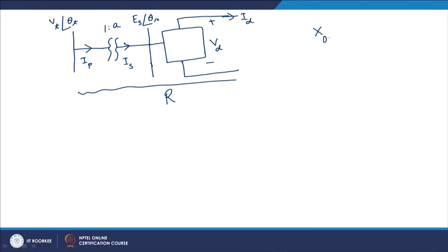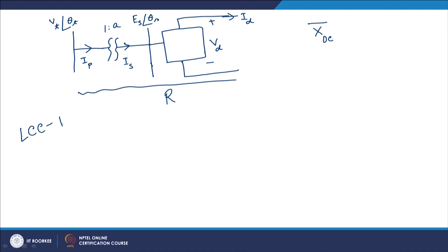Now, as we have said, in the AC/DC load flow we have some unknown quantities, given by the vector x DC. We first have to understand what those unknown quantities are, and then understand what equations are available to solve for them. In this course, as already said, we are talking about LCC HVDC only. Line commutated converter based HVDC is nothing but thyristor based HVDC.